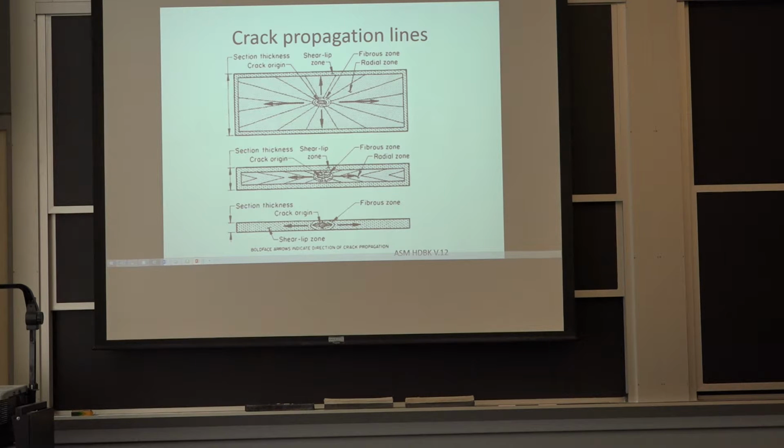In the case of this shaft, I think we were saying it was relatively easy to initiate cracks because we didn't have just one. We had one on this side, one starting from here, and another one there, and you can see the step where they try to merge. So by knowing that it was 3 cracks, we can eliminate the idea that it had only one defect in the entire section. There were at least 3 defects.